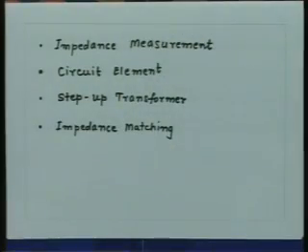We are discussing applications of transmission lines. We saw the application of transmission line for measuring the unknown impedance at high frequencies. As pointed out, at high frequency the measurement of phase is not very reliable. So, one would like to estimate the phase indirectly without doing the direct measurement of the phase. So, as we saw, by using transmission lines, just by measuring the magnitude of the voltages on transmission lines, we can find the voltage standing waves, their parameters, and from that we can indirectly estimate the phase of the unknown impedance.